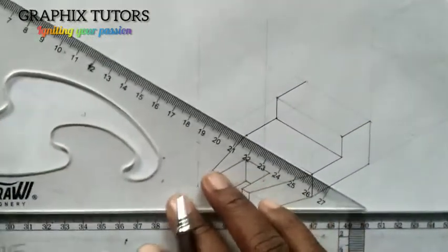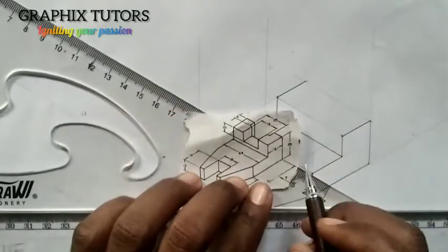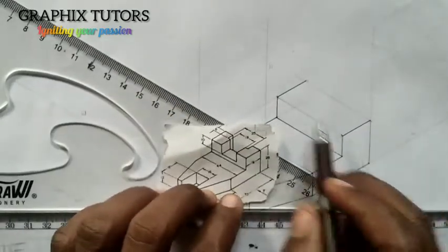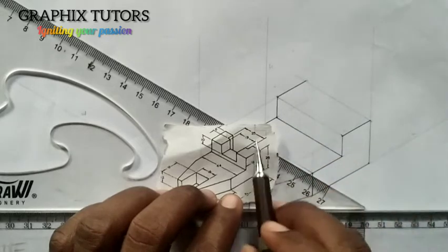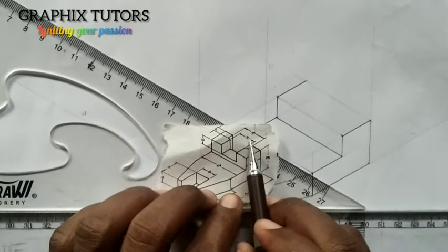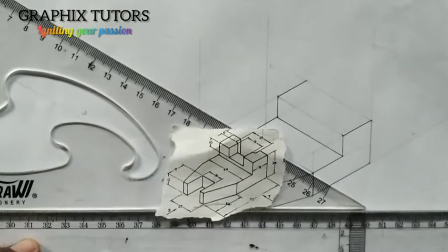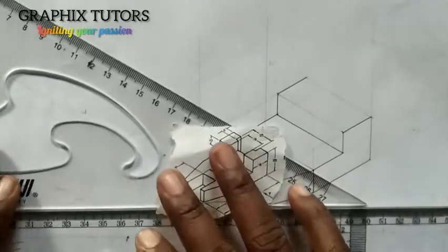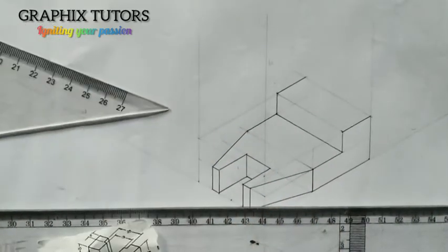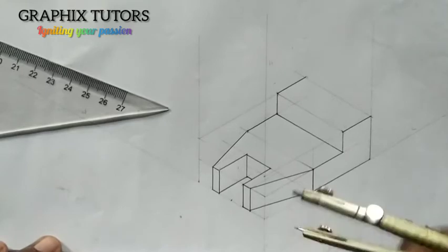So we want to start. Now if you look at this now, I'll get the center of this point, which is 44, and I'm going to measure half of 19 and half of 25. Half of 19 is 9.5, so I'll measure 9.5. First of all, get the center. So the center of 44 will be like what we did here earlier.